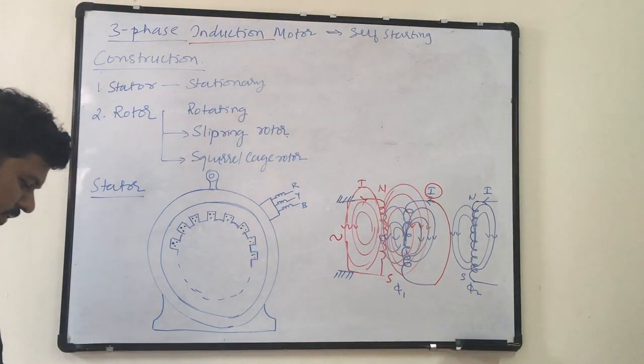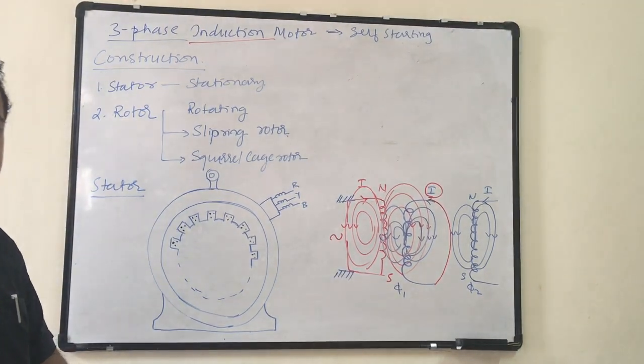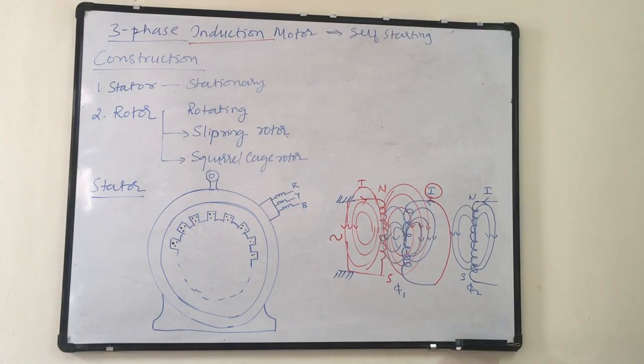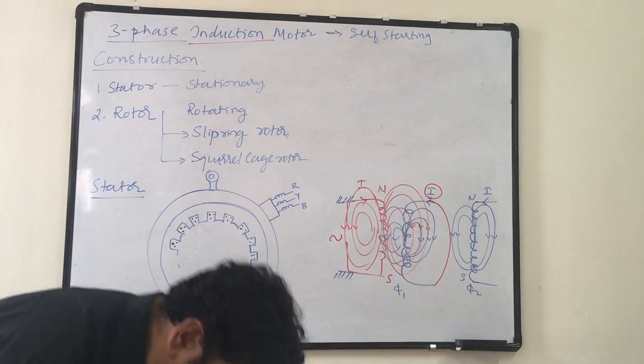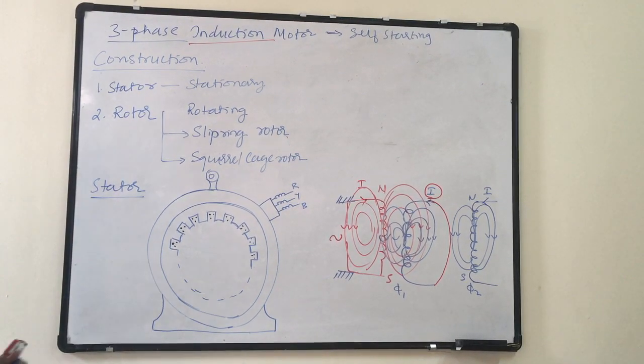Please note the difference: in the synchronous generator we had in the terminal box the DC supply also, plus and minus terminals for VDC, but in the three-phase induction motor I give only a three-phase supply to the stator. There are no other connections there, provided it is one type of rotor. For the other type of rotor we don't get any connections either, but you just remember this. So it is exactly like the synchronous generator stator.